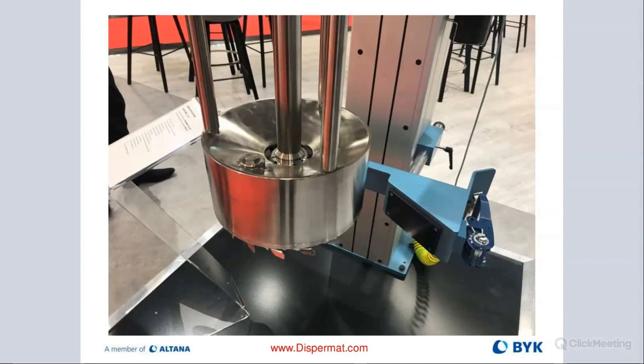We have a very efficient basket mill design. Our screen is on the bottom. We don't have screens on the side like some of our competitors. The huge advantage is that there is much less wear on the equipment because of the way the beads get thrown around inside of the milling chamber. If you have screens on the side, this is where you will experience most of the wear. That's one reason. The second reason is most of your energy gets created right in that area, so we want very good cooling in that particular zone. So we removed the screen and made that whole thing double-walled for excellent cooling capability.